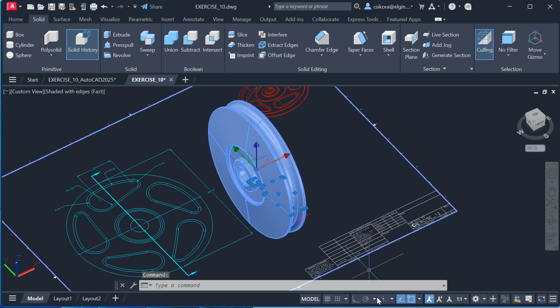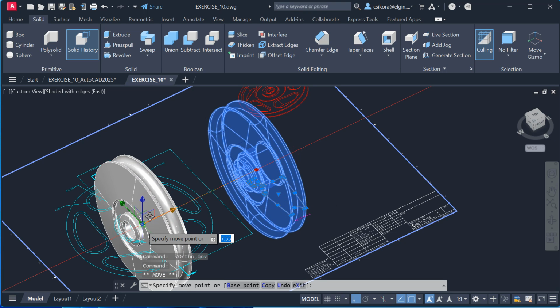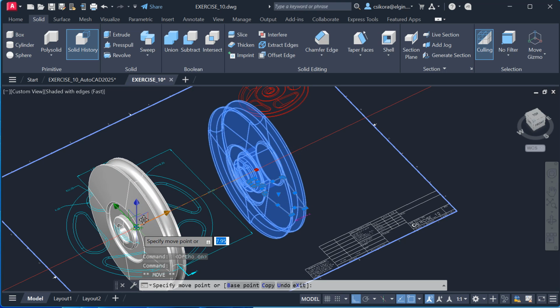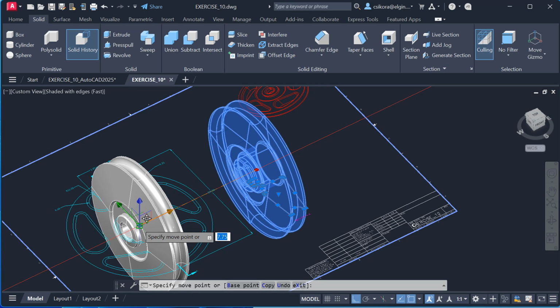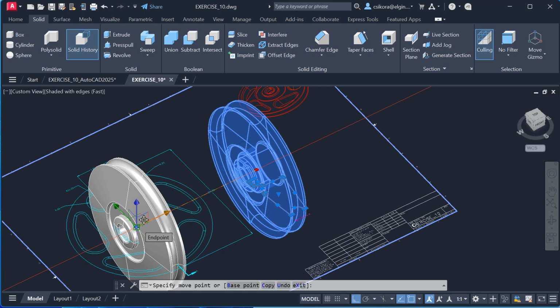And I recommend turning on your perpendicularity restriction cursor. So click on that. Now you could grab this red arrow here, drag it, and accurately get it to where, see there's a blue dot that you're dragging? It's in the center of the three crosshairs there. Get that where it actually hovers over this endpoint. Or sometimes I think it said center point. They're saying endpoint, but I think that's it.